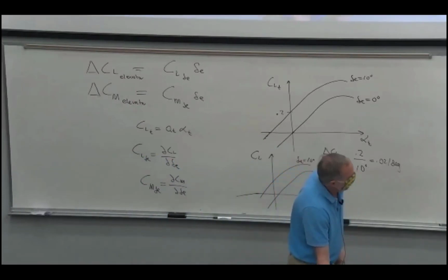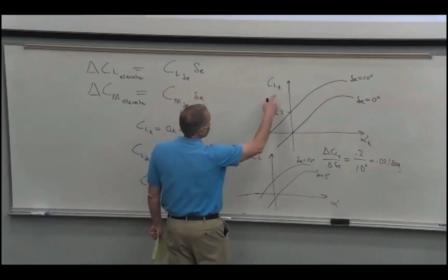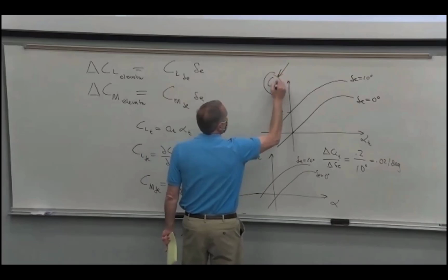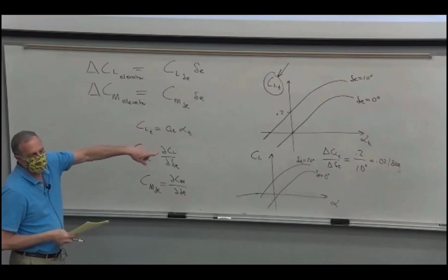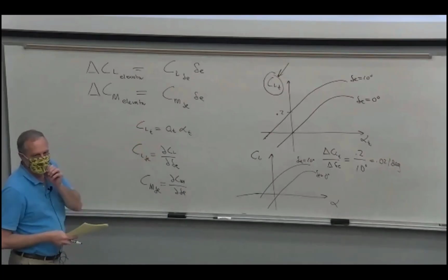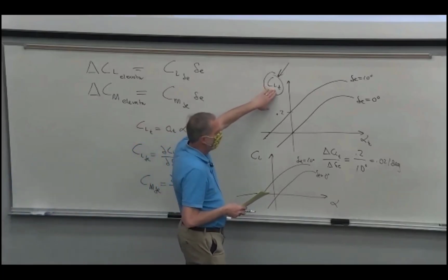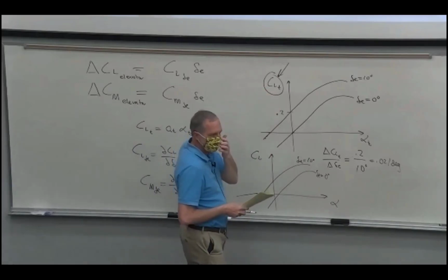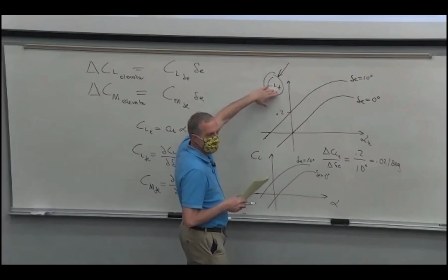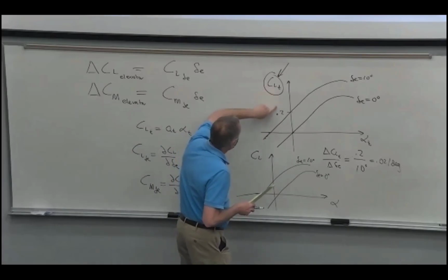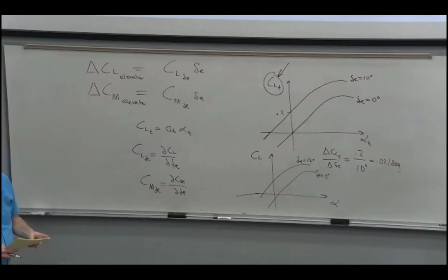then we multiply by how many degrees of elevator we have, and that's how much delta CM we get. So typically we calculate the lift of the airplane as the lift of the wing plus the lift of the tail, and we'll normally know from charts in the back of the book how a flap on a wing changes its lift. And so we'll be able to predict this from the charts, just like that's how we got the lift to add into the total lift of the airplane. So we'll go back there and we'll get everything in terms of the tail itself, all by itself. And so we need formulas on how to add in the tail into the total lift and the total pitching moment to get these numbers that'll go into our formula.